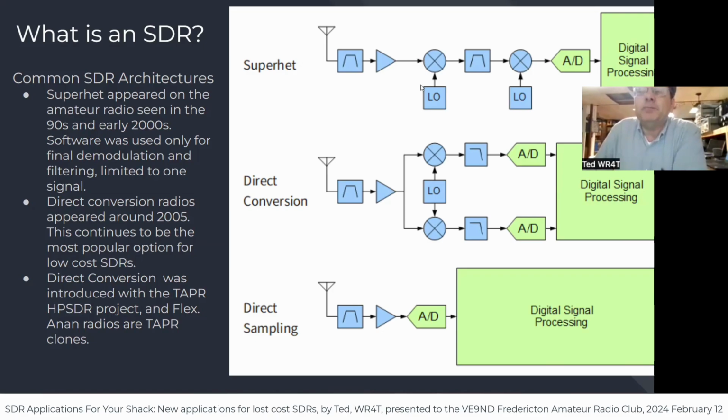So by doing that last function with a low-frequency IF, typically this second IF was like 50 kilohertz, almost like back in the 1930s and 40s with the low IFs in radios back then, they would implement an analog-to-digital converter, and then do the detection, the product detector, and the filtering, all at low frequencies. These were typically Analog Devices DSP chips, the SHARC family, Blackfin, or the Texas Instruments TMS digital signal processors. They were really designed for audio frequency, maybe up to a couple hundred kilohertz.